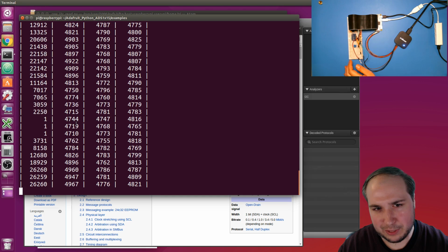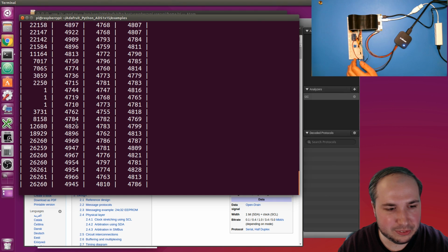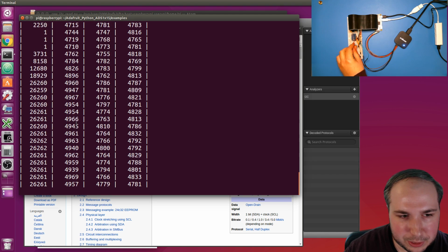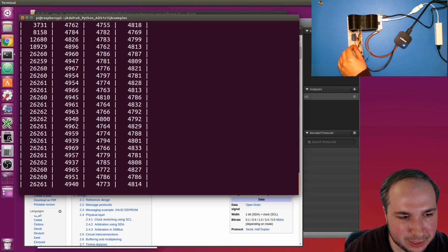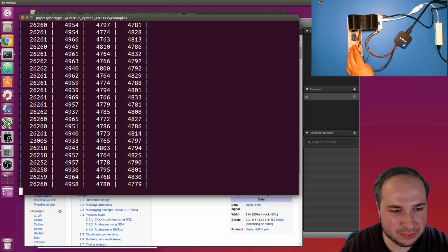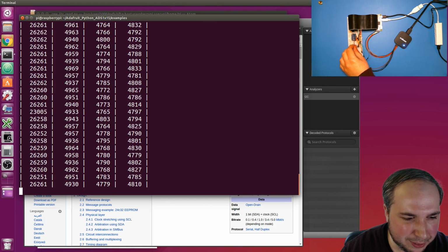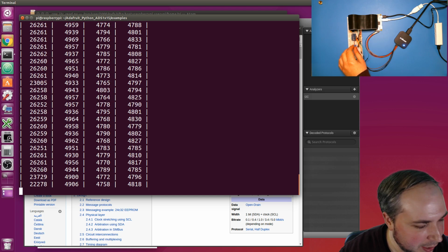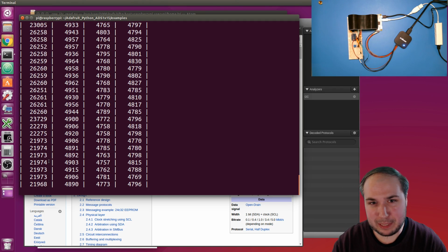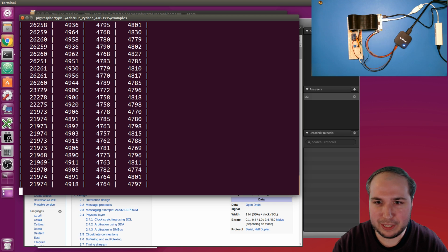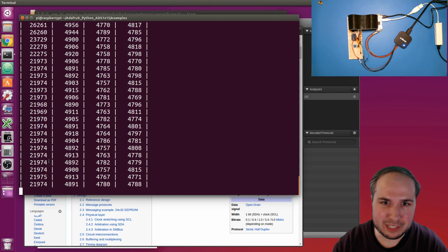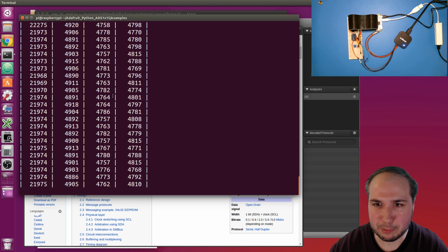I have the gain tweaked a little bit. One neat thing about this ADC is that you can change the gain to let you look at a signal that might be at a low level. So my max value here goes from 0 to 3.3 volts, which equals about 26,000 or so, roughly. But that's just showing you the value. So I'm measuring that data, and what's happening behind the scenes is I have a little Python script. It's calling a library that I wrote that's making I2C communication calls to the chip right now.